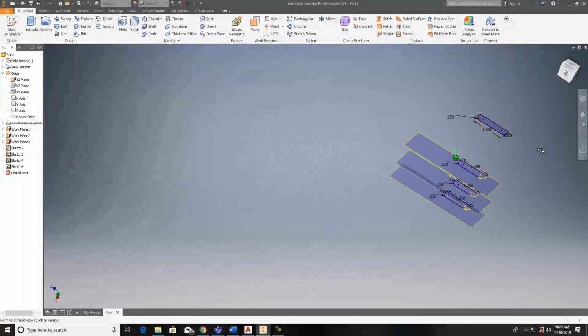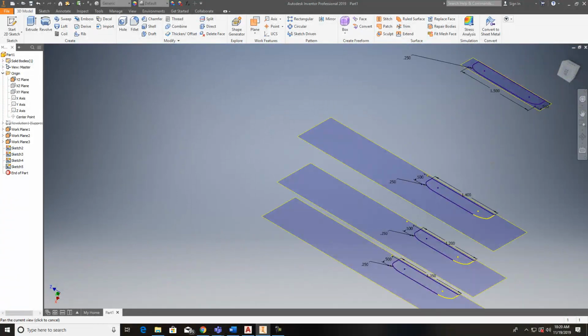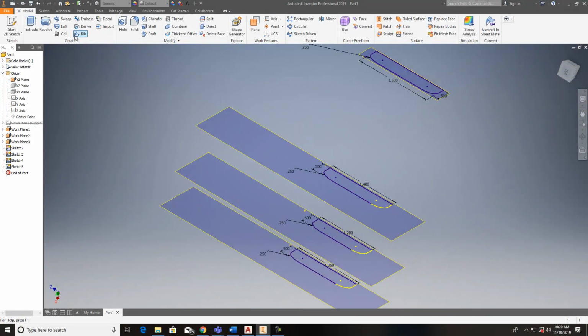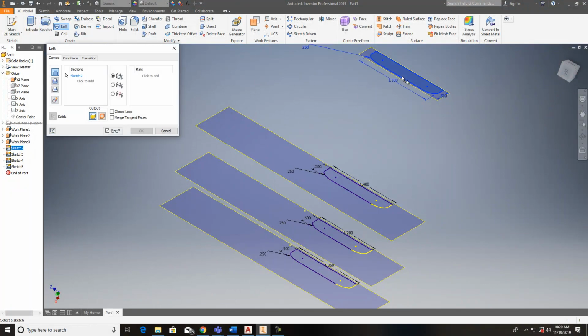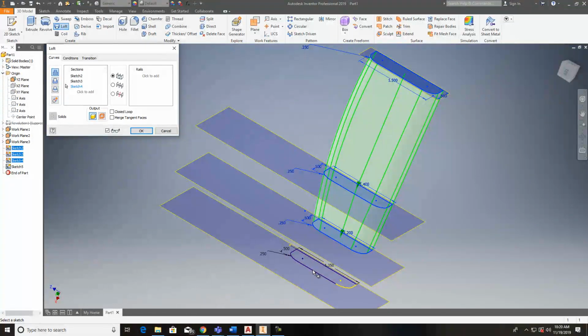I'll finish that sketch out, and you can now see the hairdryer handle starting to come out. What you're going to do is loft. It's going to catch this profile, and it's going to loft to a 3D solid. So you come up here to your loft in your 3D feature mode. You click on that one first, and you come down here and click on this one. See how it's lofting, and then you keep clicking, and you come down here and catch this one.